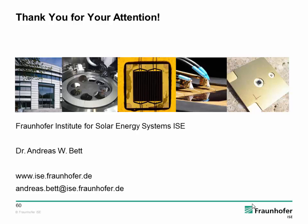I mean, as a scientist, I'm very much interested to get the highest efficiency as possible. But in reality, you have to look at what is the real benefit. It goes a little bit in the same answer. We have to look at cost. And in addition, as said, the efficiencies are really measured in the laboratory. If we go outside, we all know that we have the AM1.5 spectrum and we have to look at the influences of the spectrum. So we published a lot on that already years ago. What is the influence of the spectrum if you go to more junctions? Is it beneficial or worse?